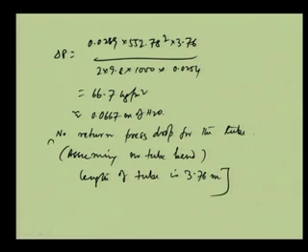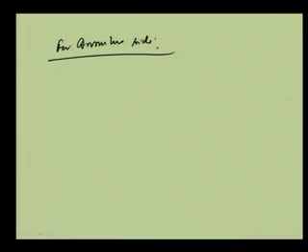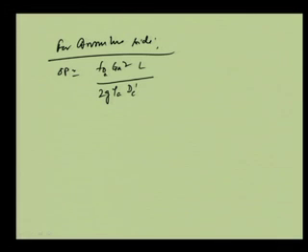So, if there is a tube bend, then we have to calculate this. We are not calculating that part. And then for the shell side, or say annular side, delta P again similarly is FD GA square, GA square into L by again 2g into rho A into DE dash. This is the equivalent diameter, and that has to be calculated.